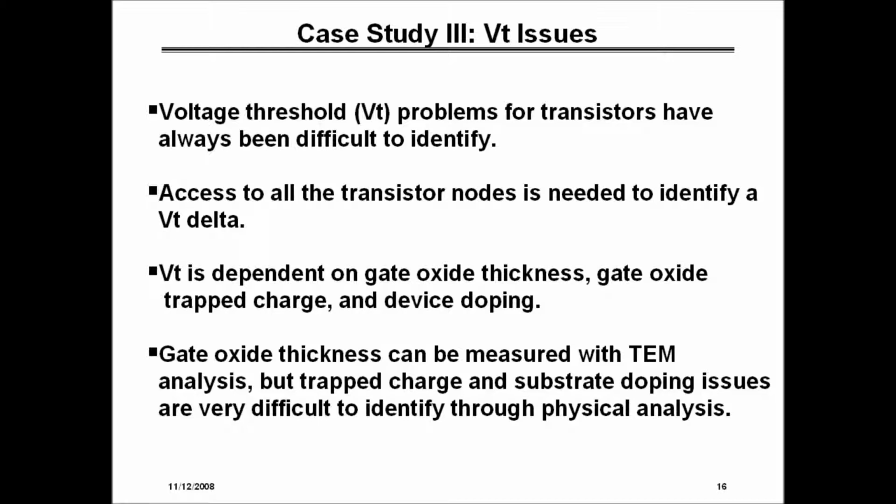And once we began nanoprobing, we were able to start finding a lot of VT issues, which in the past would have been no defect found failures, which probably ran at about a 10% level. But with nanoprobing, we could more closely analyze those types of failures, and we find a lot more issues now. And we've been able to reduce our no defect found problem significantly.